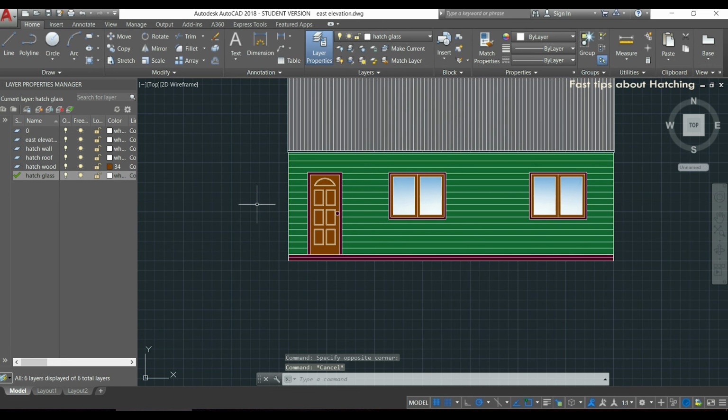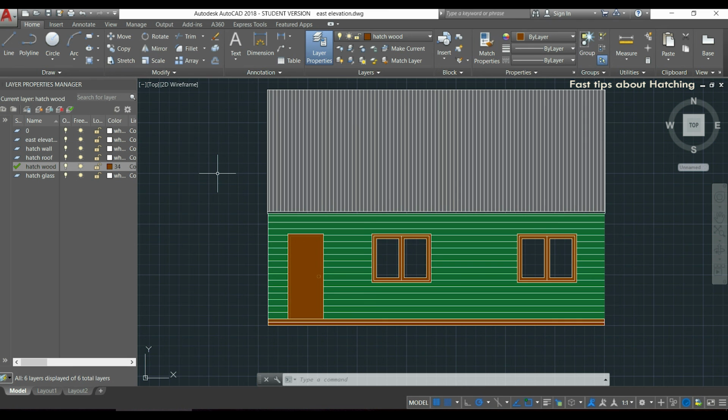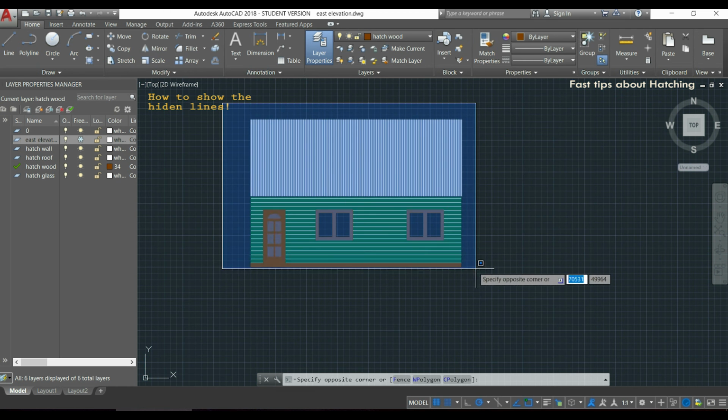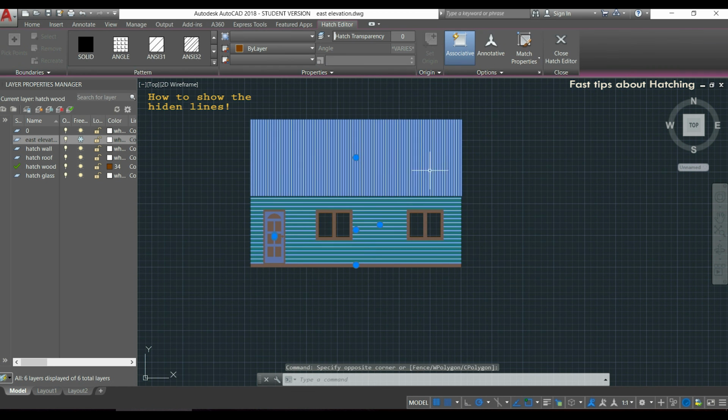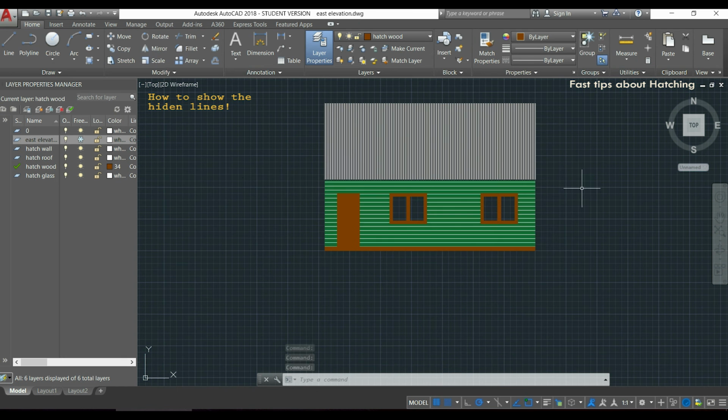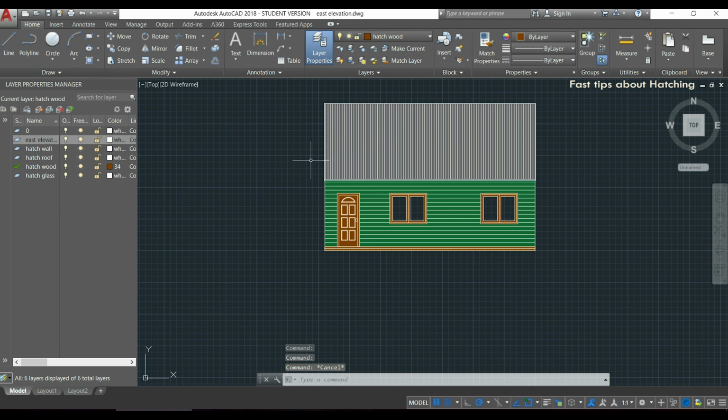Here it is. In this example, you can see some objects overlapped with lines, which makes them unable to see, as it happened here. To solve this, I can simply freeze the layer where I have all the lines, then select all the objects, click with the right button, go to Draw Order and choose Send to Back. Then I go again to the layer and unfreeze it, and you can see now all the lines in the drawing.